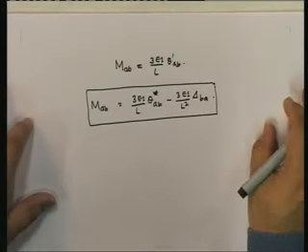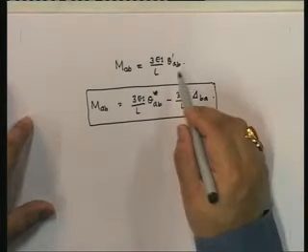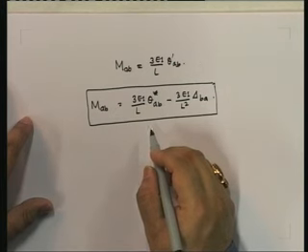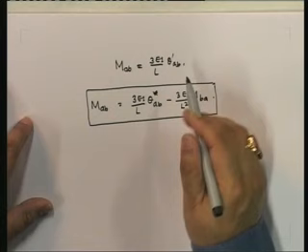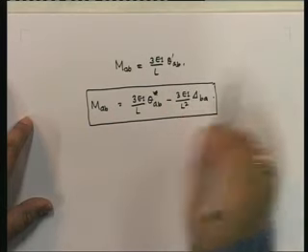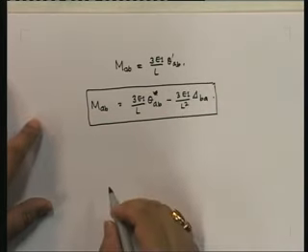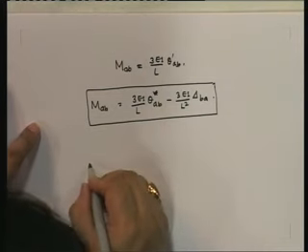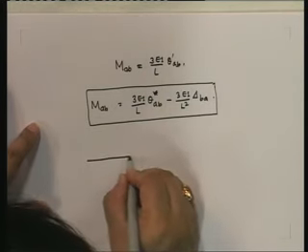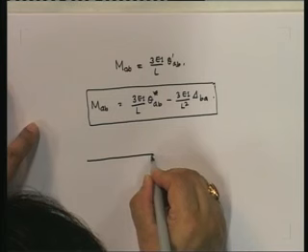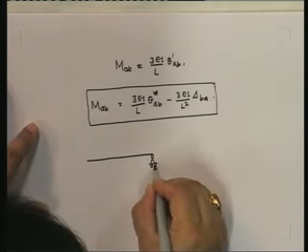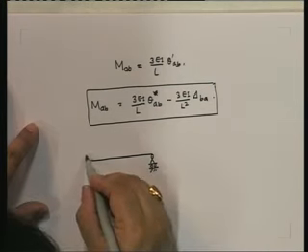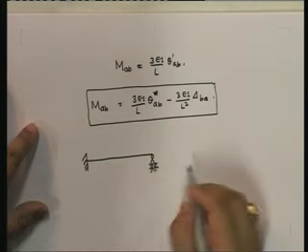Now, what about the fixed end moment? Up till now, we've not considered the fixed end moment. Now, you see, the advantage of this is that I can consider the fixed end moment separately and add it, because it's after all superposition. So let's look at what happens. To consider the fixed end moment, it's very easy.